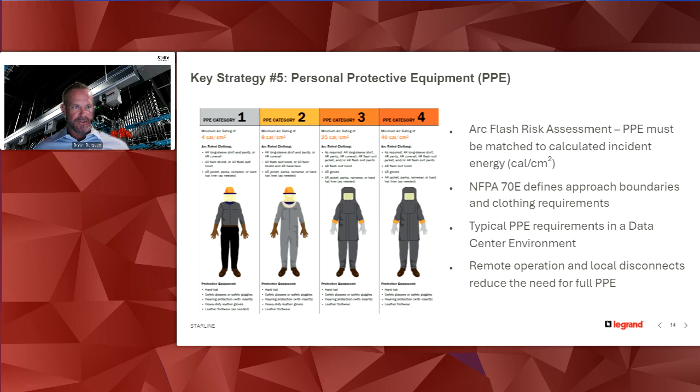And then like Chris was talking about with the remote plug-in adapters that we have for our tap box units, I've seen those, those are great, right? So that it pulls you out of the arc flash risk boundary, because you've got a tether. So I've also seen them used on switchgear, to where we actually mount an external operator that controls the control handle on switchgear. So when you're doing any kind of operation, you can mount that to the gear, stand back from it, and you're out of that arc flash hazard area.